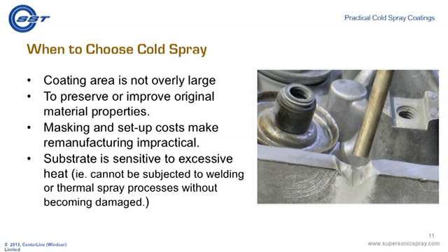Okay, so you've seen a couple of examples, some case studies where we've shown you some SST cold spray application. Of course, the question becomes, when do I know that cold spray is the right repair solution? So when do you choose cold spray? You choose cold spray when the coating area is not overly large. You want to preserve or improve some original material properties.